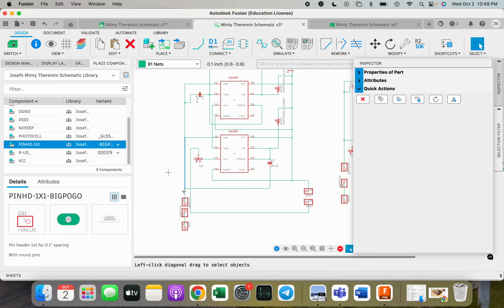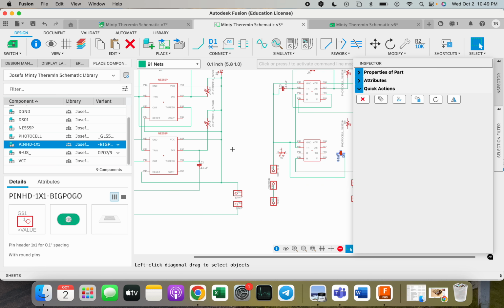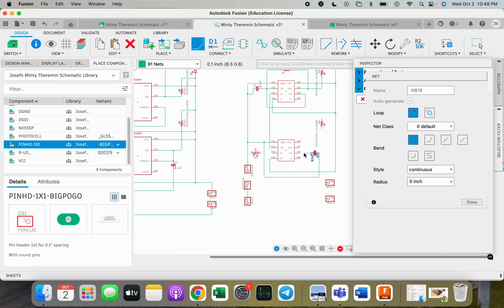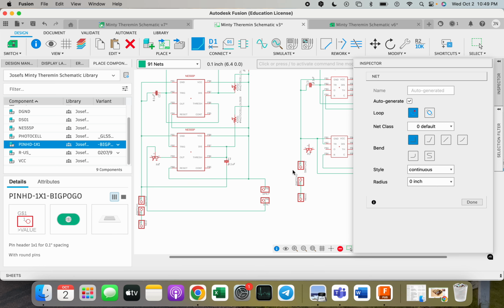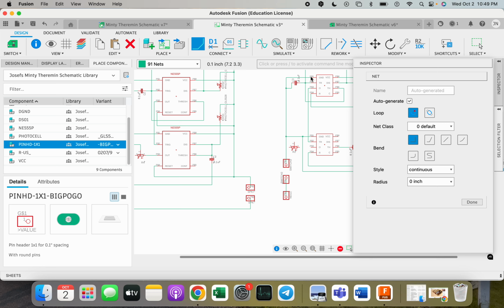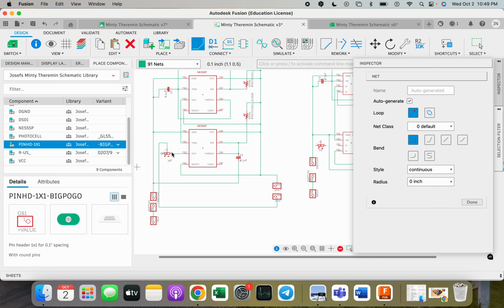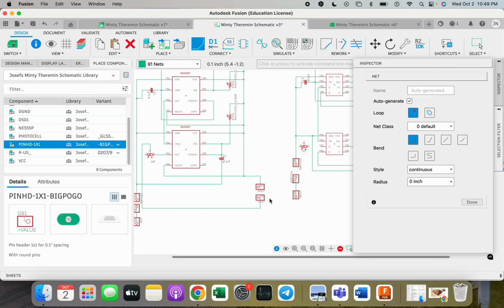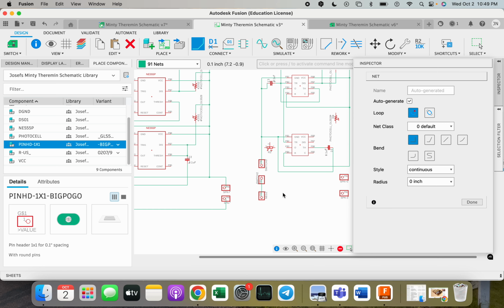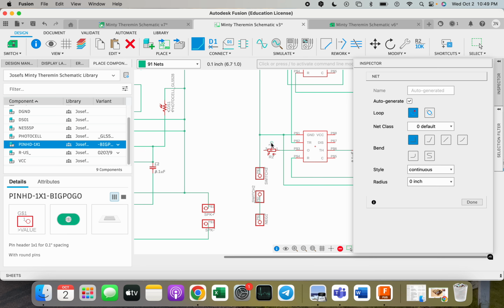So pin 1 is connected over to capacitor 1, and capacitor 1 is connected over to pin 6. So let's finish that line connection, and then we'll go back to pin 2. Pin 2 on the lower is connected to pin 3 on the upper. That's already done. Pin 3 is connected to the pot, to designation 1 of the pot, then comes out of number 2 and down over to the negative terminal of the speaker. So we're going to go from pin 3 to pin 1, and then we're going to come off of here,